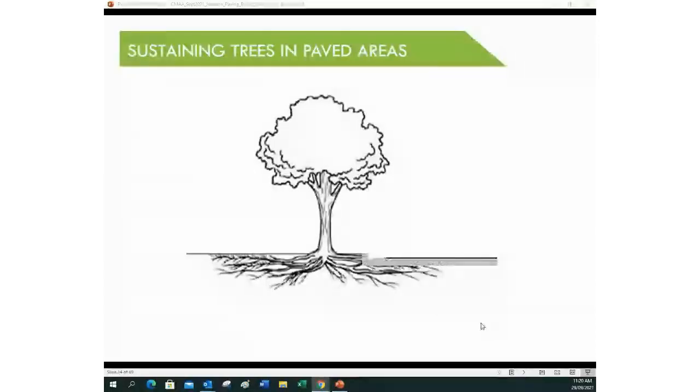Anyway, we come along and we excavate the fine roots and we'll put a road pavement down or dig a trench and put a pipe in and then come along and compact the soil and put a footpath in. So you can see the diffusion is greatly reduced. The tree starts to suffer. The permeability decreases with compaction. The surface is sealed, so water doesn't enter. Gas diffusion is greatly reduced, trees start to struggle. Trees are dynamic, they do respond slowly. They will grow where conditions support growth. And what generally happens is that growth occurs at the interface of the tree roots and the infrastructure, causes problems. Anyway, that's tree root growth 101.